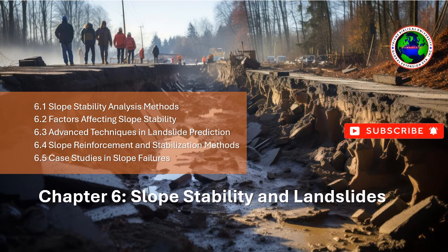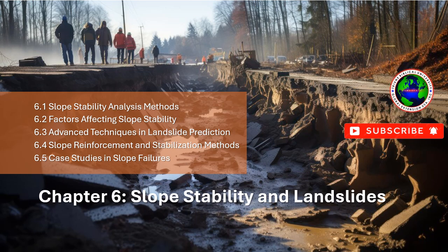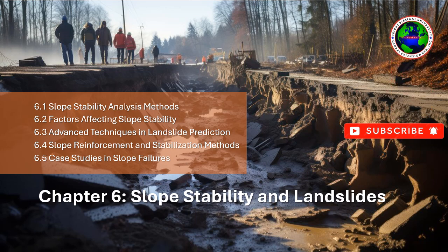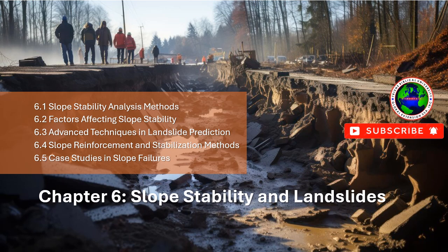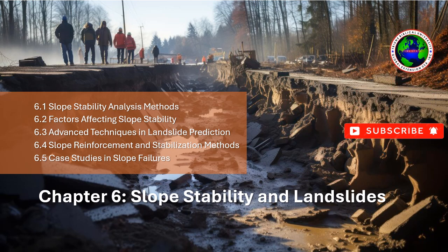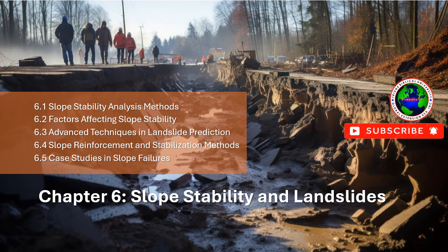Techniques: French drains. A trench filled with gravel or perforated pipe used to channel water away from the slope. Subsurface drainage systems. These systems, such as horizontal drains or interceptor drains, remove water from the soil before it can accumulate and reduce stability. Surface drainage channels. Shallow channels or ditches placed on the surface to direct water runoff away from the slope face.